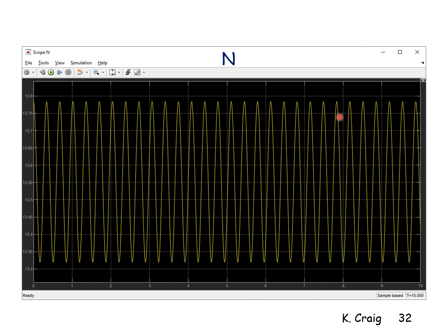But we notice the oscillation is twice the frequency of the oscillation of theta because the normal force, as the system goes through an oscillation, goes through 2 cycles of variation between extreme values. You can see this from the simulation itself. So we notice that the normal force here is changing at twice the frequency of the oscillation, and it changes in a sinusoidal way between these two values, 13.3 and 13.8 newtons.